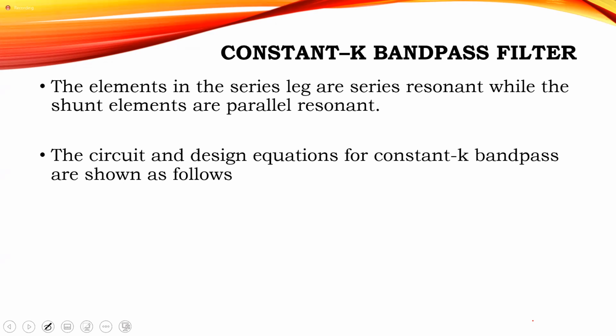If I attenuate the frequencies I don't want, I must have the low impedance to that in parallel. Now, if you think about that, we're saying we have a series resonant in series and the parallel resonant in parallel.